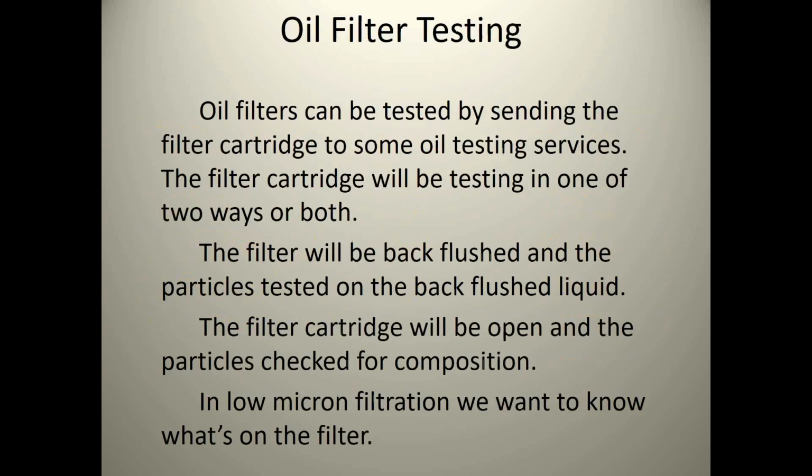Now, when you start filtering your oil down to these real low levels, when you send your oil analysis samples in, the results you get back are going to be very low. You're going to have the oil cleaned up. But the purpose of this slide is don't throw the filter away when you get done, because that's where all your particles are. So there's a number of labs like Test Oil or Insight that you can send the filter to. They'll backflush the filter, tell you what's on the filter, and send you pictures back of what's on the filter.